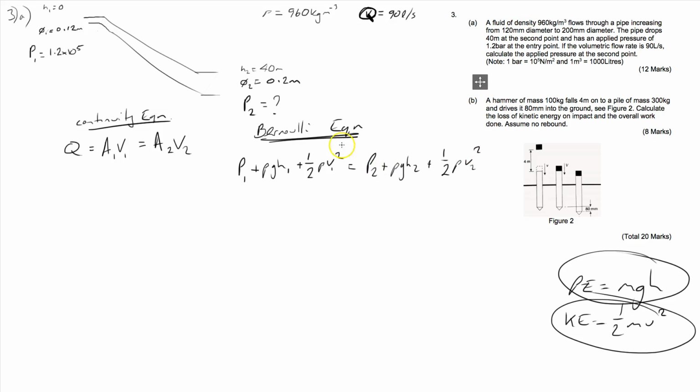In other words, the total sum of the pressure, the potential energy due to the head, and the kinetic energy due to the movement of the water is maintained. We're not somehow, by means of a pipe, creating or destroying energy. If we could do that, then I'm sure Stephen Hawking will want to know about it.